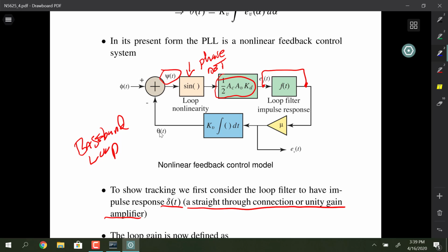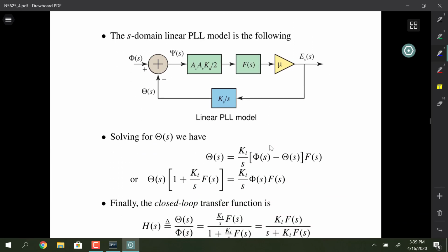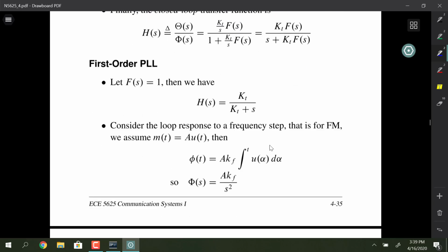We're going to move on and be looking at the complex baseband phase lock loop here, and then another one I have in the notes is a full up carrier-based phase lock loop, but we'll see why that's not done very often, because it's very intensive from the simulation standpoint. And of course, we linearize the loop along the way, so we could use Laplace domain analysis to look at it as a feedback system and do linear systems theory work with it.